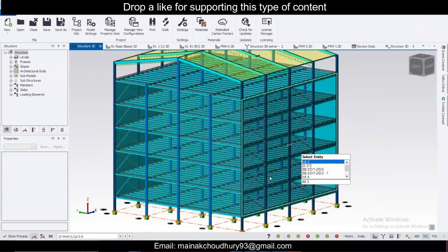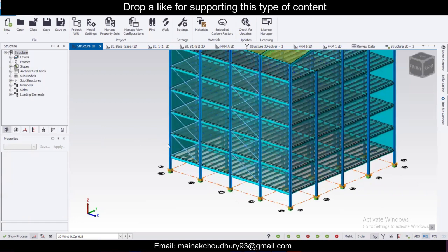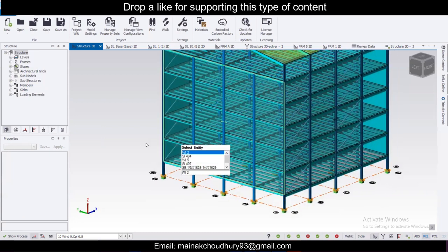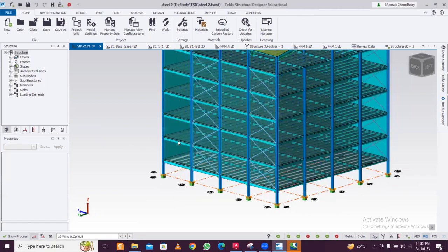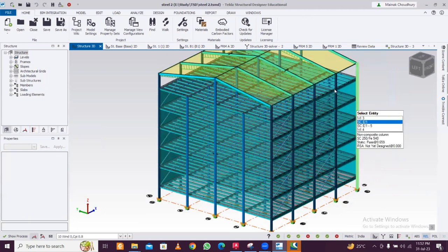And another thing, if you want to provide bracing in this direction also, you can provide, especially in the back direction, and in the front direction, apart from the openings or where you will have doors, in those directions you can provide bracings. So it will provide more stability to the structure and protect against the drifts and all.